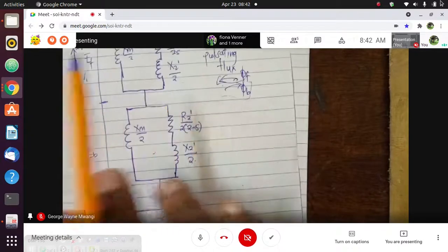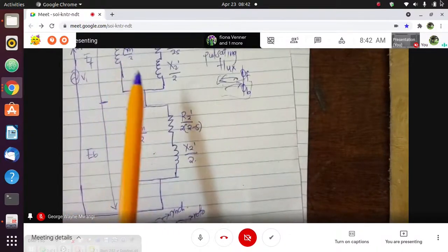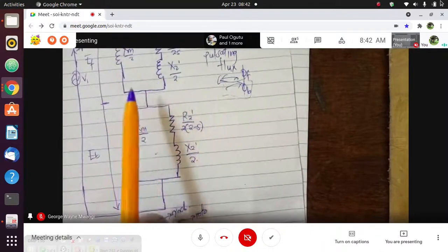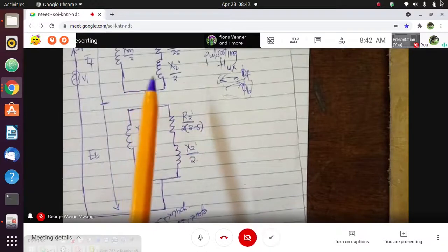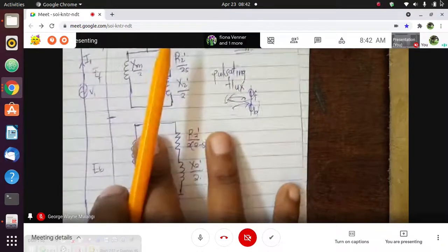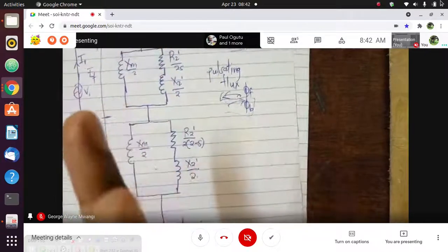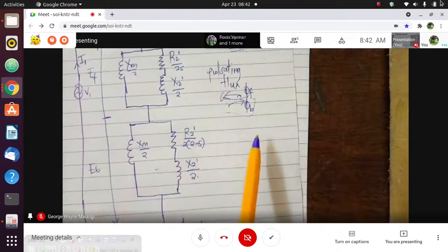Like we said, the stator flux can be resolved as two fluxes rotating in opposite directions. These fluxes induce a current in the rotor, such that a single phase motor can be seen as having two rotors, each having half reactance and half resistance.